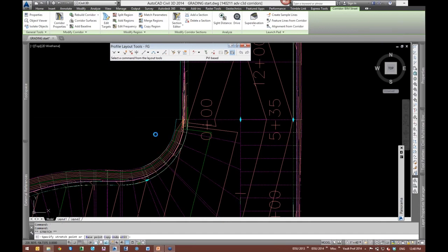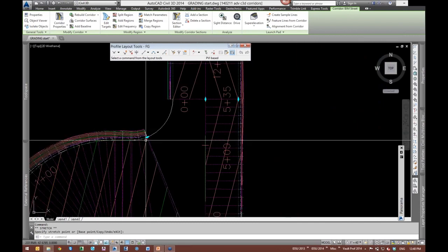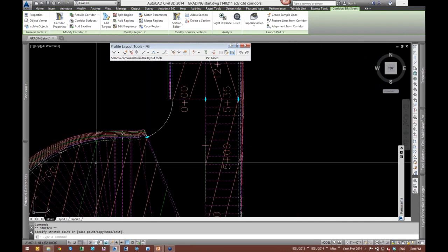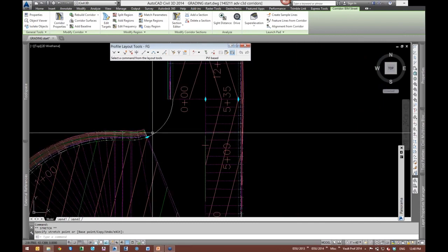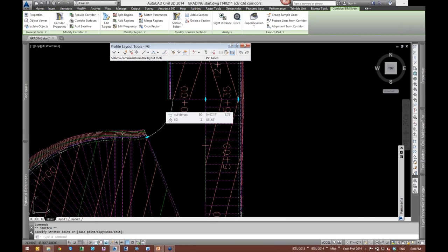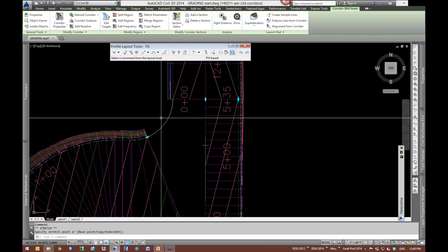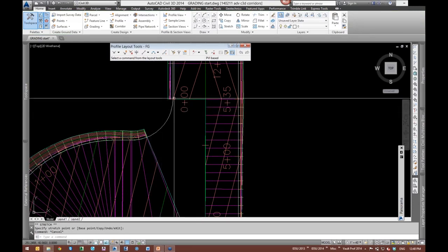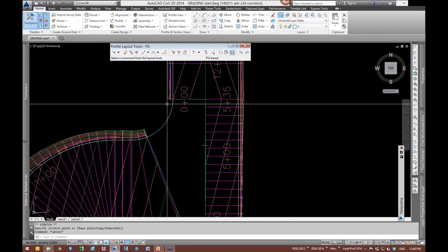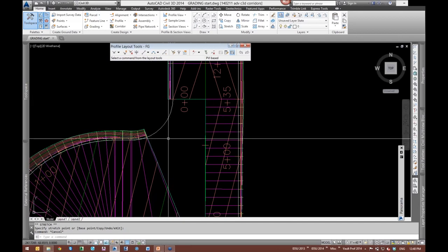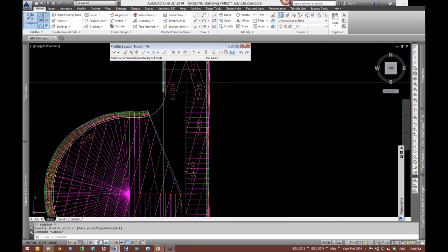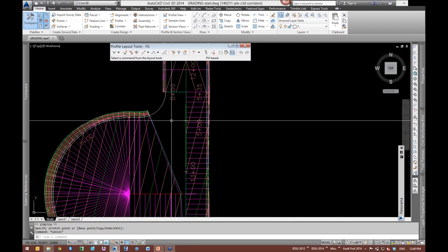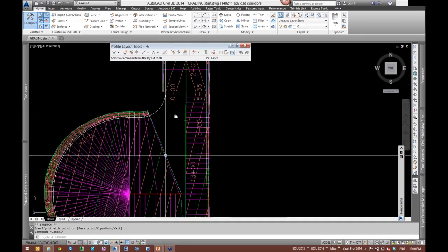And you need to model another region in the exact same way we modeled this one, except the profile right in here needs to be a separate layout profile. So that's a little less dynamic in that way, but there's almost no way around that. You have to manually design that transition profile in there. So again, you would back this off, target these same alignments and profiles.